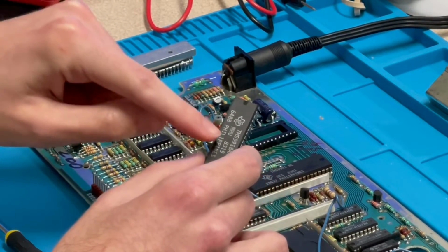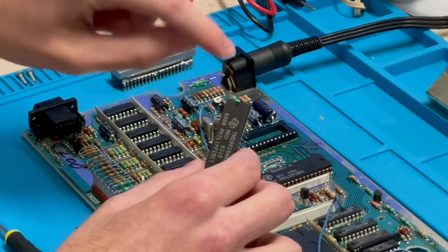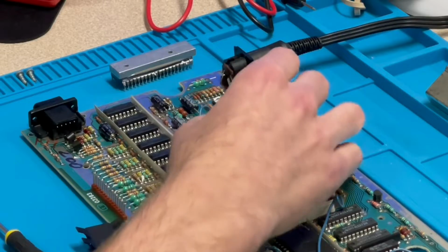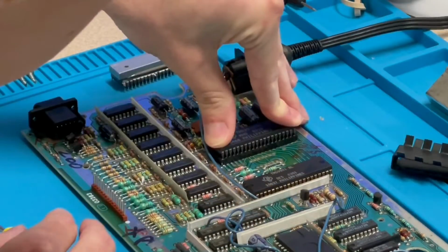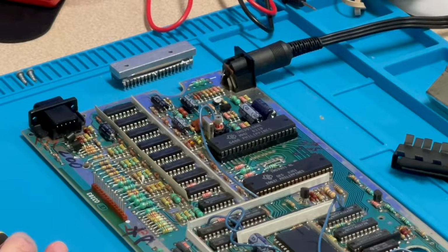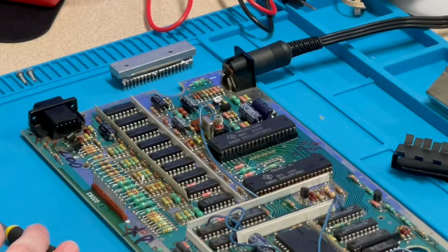And pin 1 of this chip is up here, so I have to make sure that the little notch on the chip here faces down like that. So that's the way it'll go into the socket. And there we go. There's the video chip installed. I'm going to leave the heatsink off of it this time because I'm only going to have it running for probably about 30 seconds, so it should be fine. It's not going to overheat or anything.